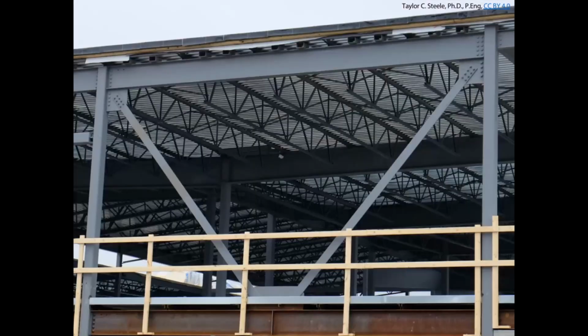But we're going to come back very briefly to this brace example in that school on the north side. We already know that this brace is carrying 580 kilonewtons of factored tension. We already know that the bolted side is governed by the net section fracture strength, which was 587 kilonewtons. We know the yield strength of the bar was 709 kilonewtons. And we know that the strength of the welds, as long as we use the 250 millimeter long, 8 millimeter welds, was something like 600 kilonewtons.